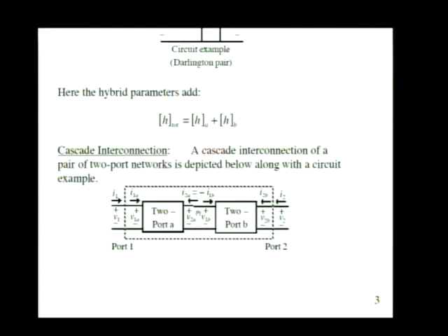However, in terms of currents, check this out. I2A is equal in magnitude to I1B, but defined in the opposite direction. You always define currents flowing into the terminal with the positive polarity in any given two-port.